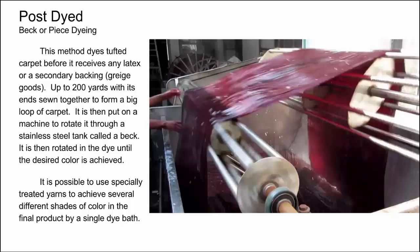The machine rotates that loop continuously through the dye bath or the Beck, and we're going to keep it rolling through that bath until it reaches the desired color that the manufacturer is going for. And remember, using specifically treated yarns or chemically treated yarns, a manufacturer can achieve several different shades of color by running it through a single dye bath.